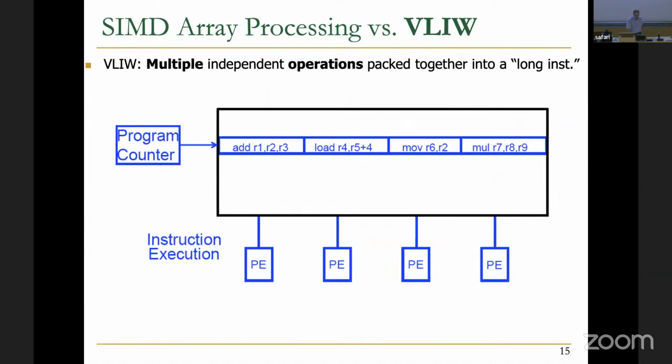Perfect. We haven't discussed VLIW in this course, but I briefly mentioned it last week when I was talking about out-of-order execution. In out-of-order execution, the goal is that we schedule instructions dynamically. The hardware is tasked to find the instruction level parallelism from your instructions and schedule them dynamically, such that they can benefit from high parallelism.